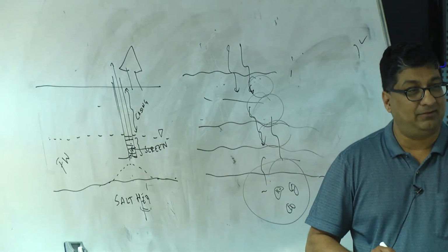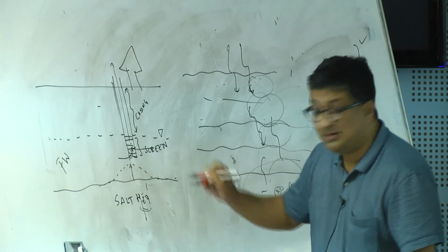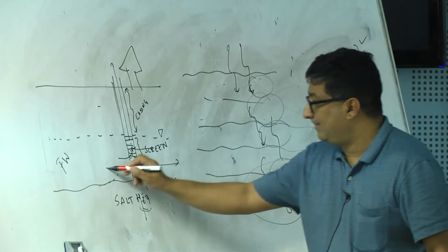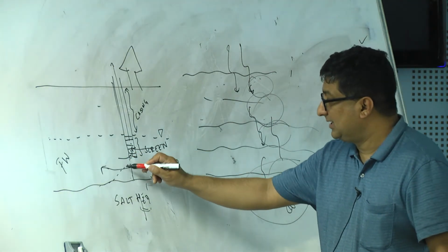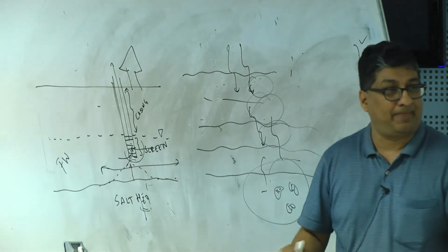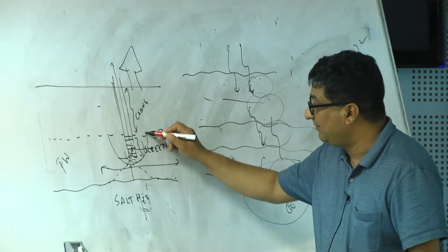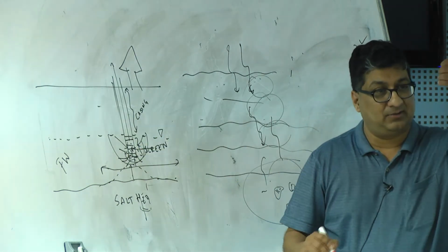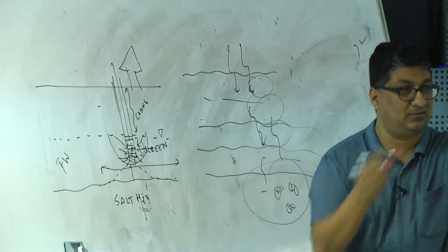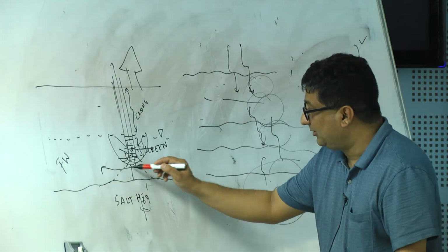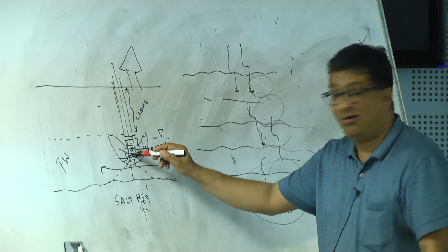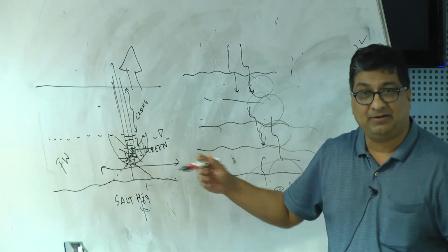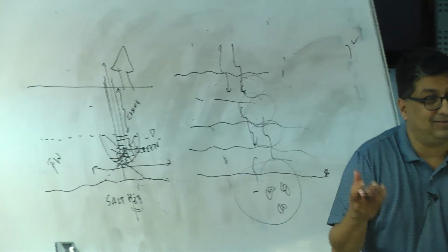Okay, there is some critical level to which it moves up. It's okay. But if it crosses that critical level, what happens is the water will simply get sucked into this well, because this well has an influence. It's pumping, it's pulling water from all directions, because it's a radial tube. Water is coming from all directions into it, and it's possible that this interface doesn't have to go all the way to the well. If it just rises enough, it will still get sucked in. If it goes into that zone of influence, or the cone of influence, it will get sucked into the well.